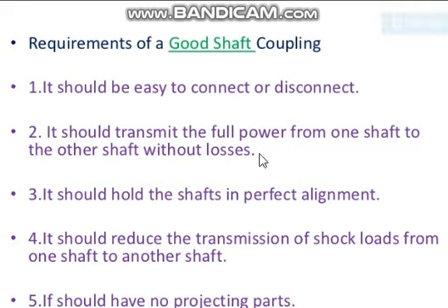Why? If projecting parts are there, what happens? Say nuts and bolts are projecting. If we go close, somebody's dupatta or somebody's full sleeves might be pulled, and a person may go into the machine, and an accident will take place. That should be avoided.